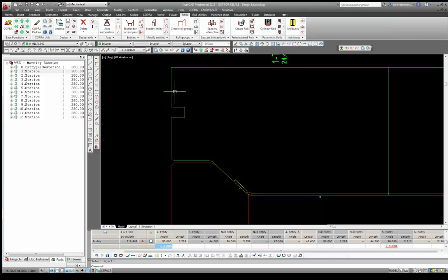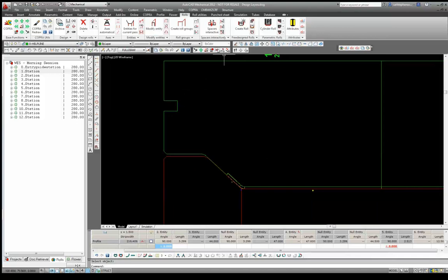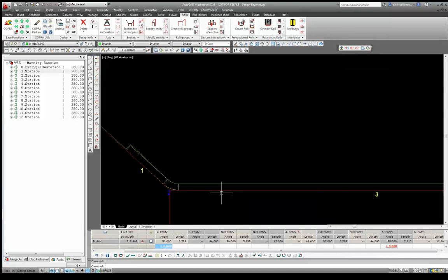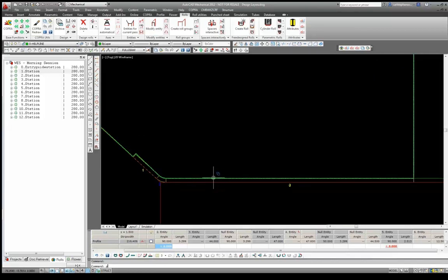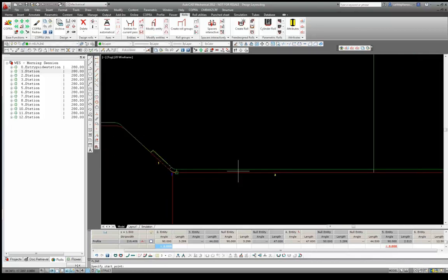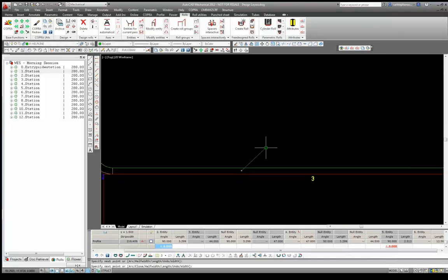So the possibilities for this, remember, if I just save the pass, if I had some reason to add some clearance, maybe the addition of a crimp or a claw, I could just then, once I know the location of my crimp and claw, obviously by using the Copra tools as mentioned in a previous webinar, I would have a polyline like this. I could go to add contour.